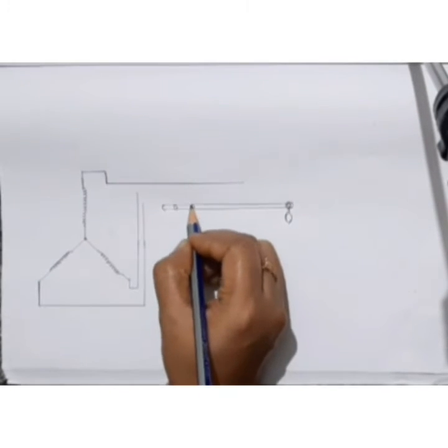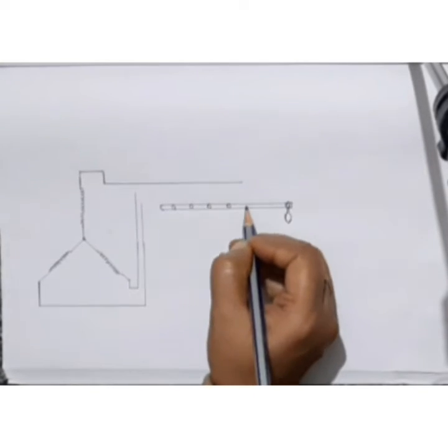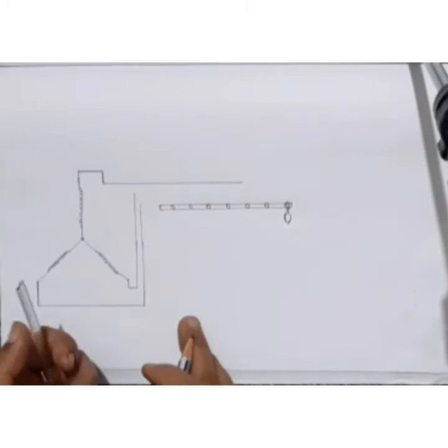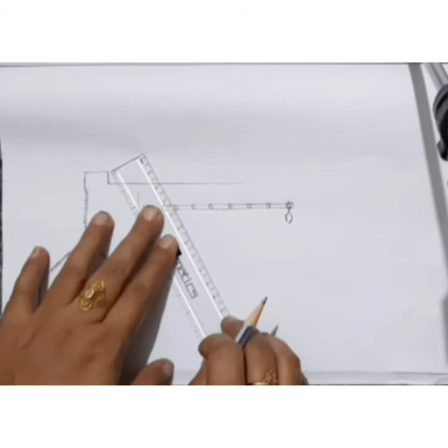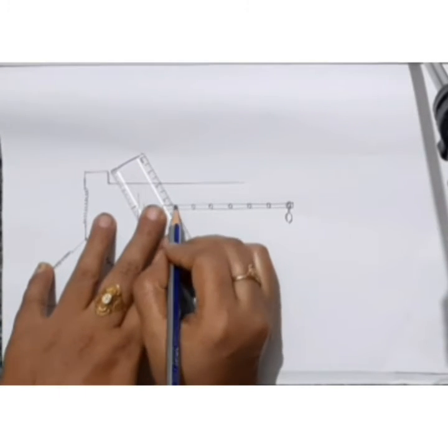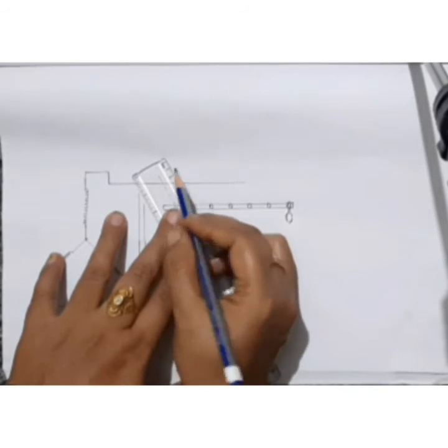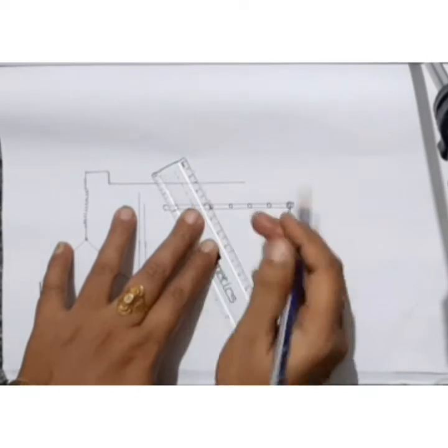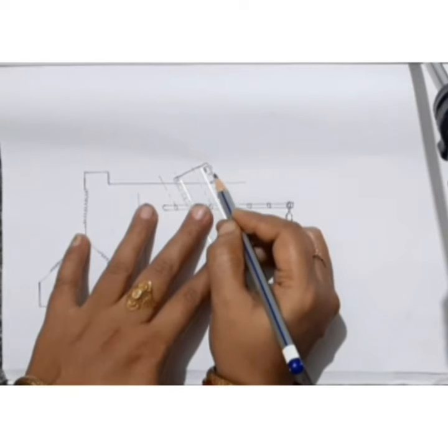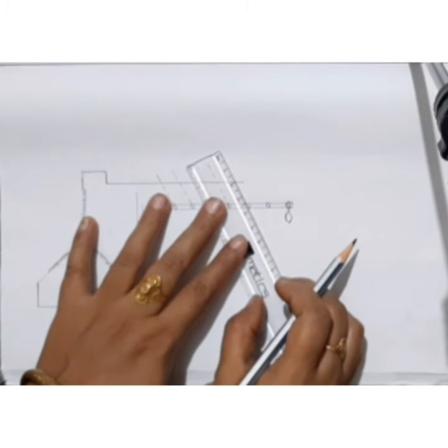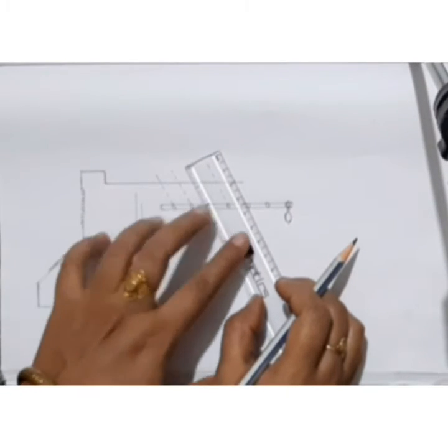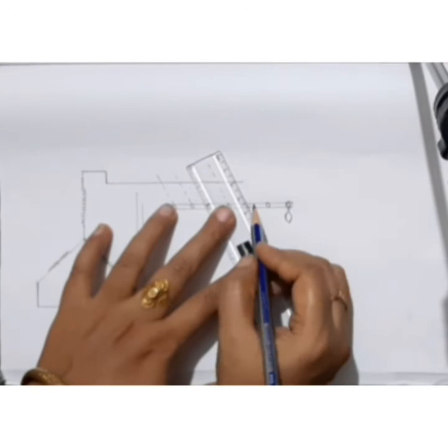Here in the diagram we will draw the starting switches and the running switches. These switches are making the changes, making contact, start or run. They may be of the air brake type for small motors or oil immersed for large motors to reduce the sparking. Most of the auto starters are provided with a 3-step tap to reduce the voltage.